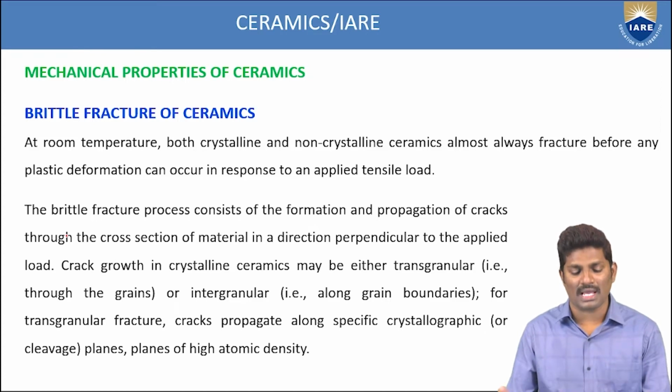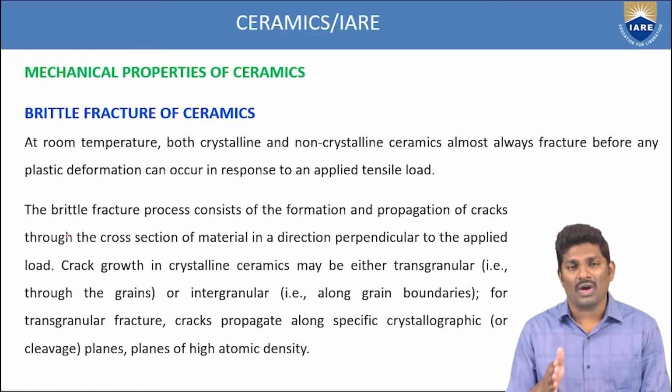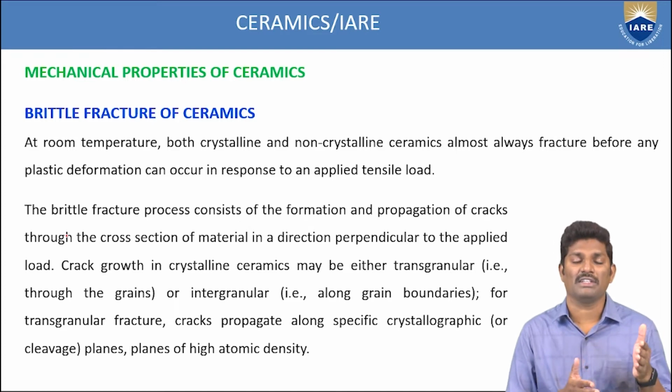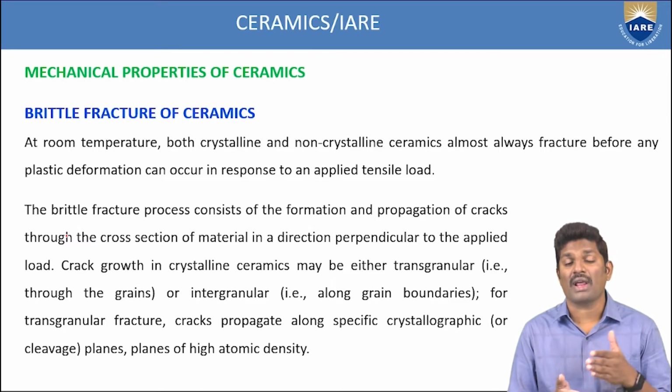So in this case, what is happening? At room temperature, both the crystalline as well as the non-crystalline ceramics almost always fracture before the plastic deformation. That means these types of ceramics are fractured, that means they are very, very brittle in nature. They fracture before the deformation only.